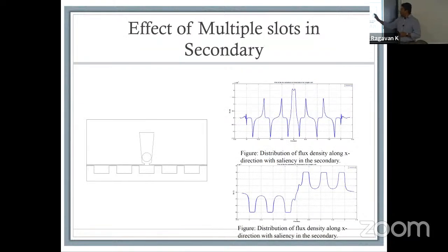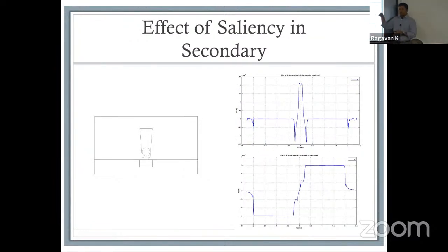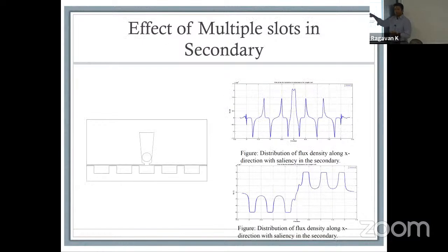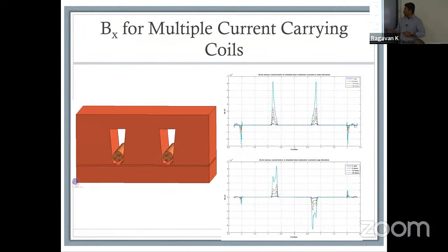So, the same idea. What you will see is that if you start adding more slots, each individual pole starts to show the presence of a slot. It's not uniform like it was before, where you have one slot and the rest of it is 0. Adding each one, every single geometry adds to the presence of your flux. The same thing happens on the tangential side as well. This is the X, because this was not a rotational or radial geometry. So for a Cartesian system, this was X and Y, and it gave you a clear indication of the presence of a slot.